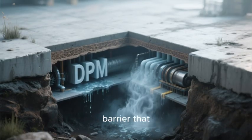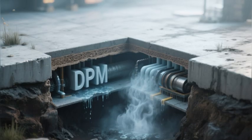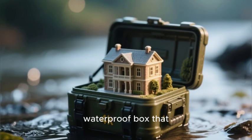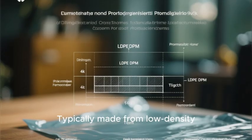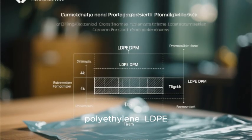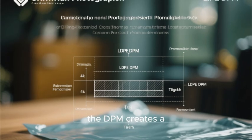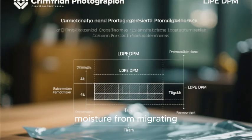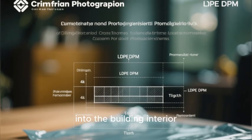The DPM serves as the horizontal barrier that separates your concrete ground floor slab from the moisture-containing ground beneath. Think of it as the bottom of a waterproof box that contains your building. Typically made from low-density polyethylene, LDPE, with a minimum thickness of 1200 gauge (300 microns), the DPM creates a continuous impermeable layer that prevents ground moisture from migrating upward into your floor slab and subsequently into the building interior.